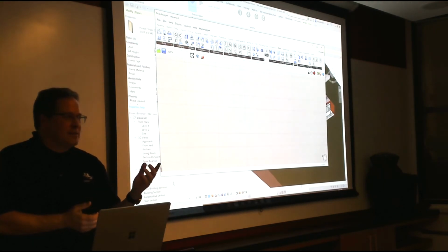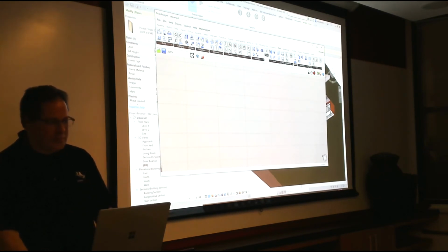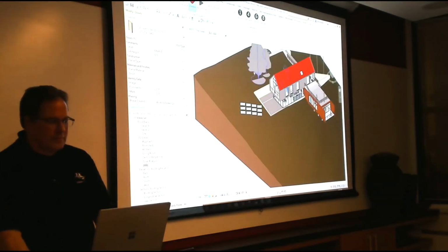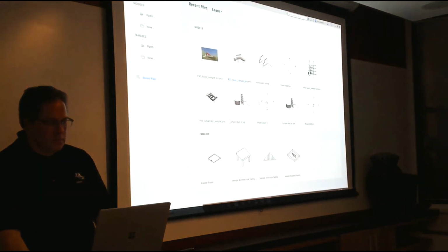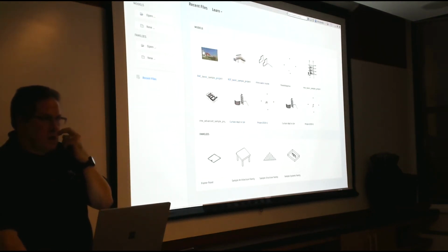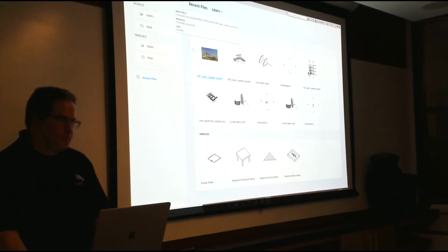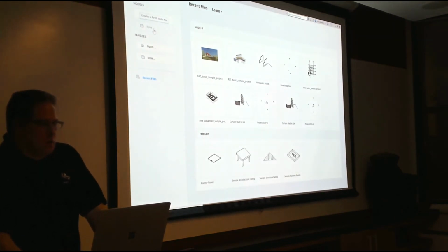Any other questions? Yeah, a lot of what I encounter is something really mundane, like drawing line work on a sheet. If it's defined in Rhino in 2-dimensional space, can it be populated onto a sheet right now with what's currently there? With the components that are currently there, no. We just haven't got to sheets yet, and Hassan can help with that. You can create model lines in 3D, so that's not a problem, and just hide them in a view.